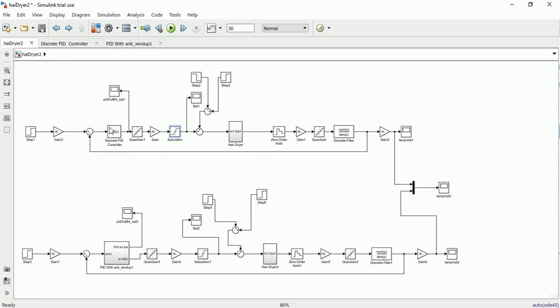There are methods to do a digital PID controller, which at the end will be very similar, but we skip that step, and we are going to assume that our sample rate will be enough for this system to work with our continuous design. And our sample rate is 100 samples per second, which means a sample time of 1/100th of a second.